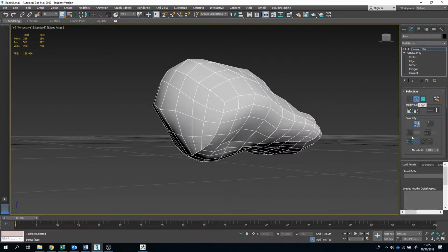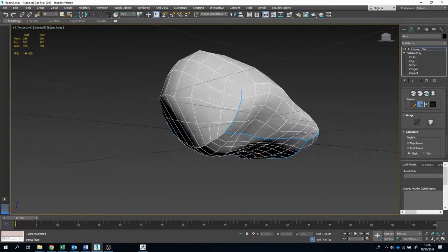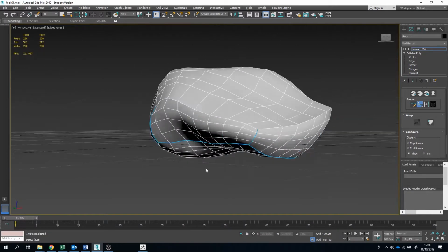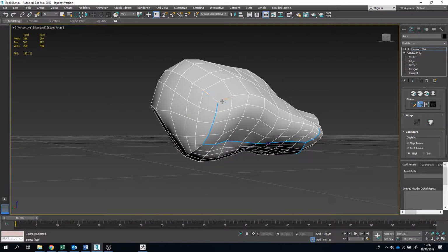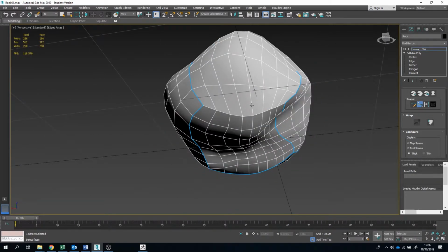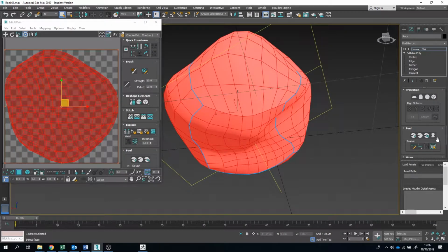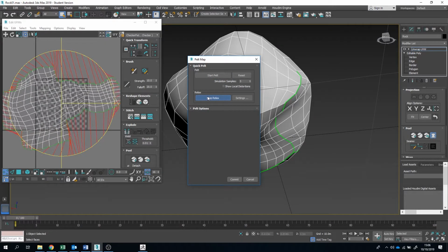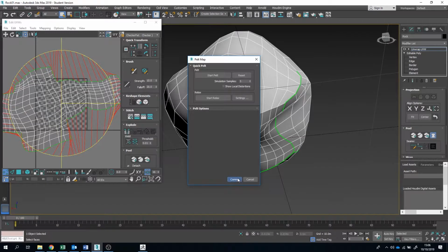After that, we selected the edge and went down to point seam and started selecting the relevant points of the model. The points of the model should reflect what you did with unwrapping a box for the first time in the first year. Look for the three edged points of the model and simply join them together like so, leaving one side without an edge on so that you can peel the model apart. From there, we hit Pelt. We then hit Start Pelt and stop and relax the UVs like so.